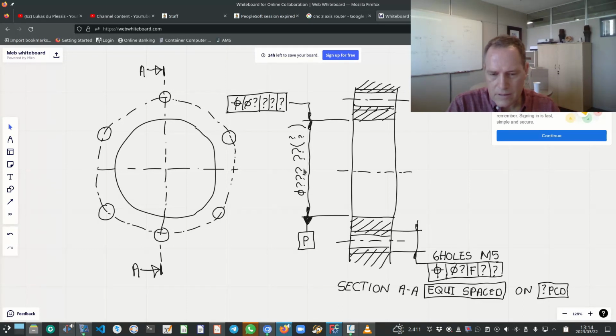You will have the size there based on your measurement, and you'll specify the tolerance using a letter and a number, and in brackets you will indicate the upper and lower tolerances for that size tolerance specification. Right, that's easy enough.